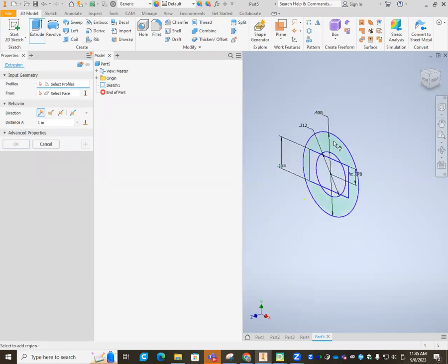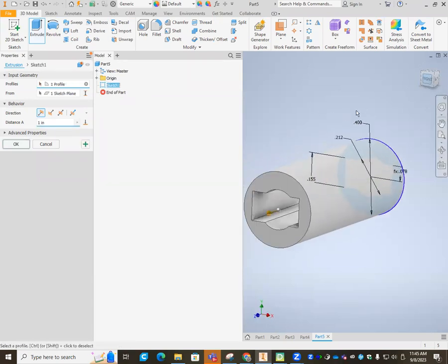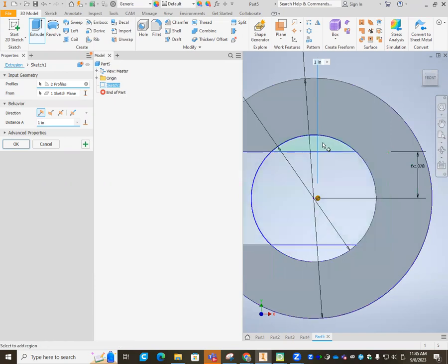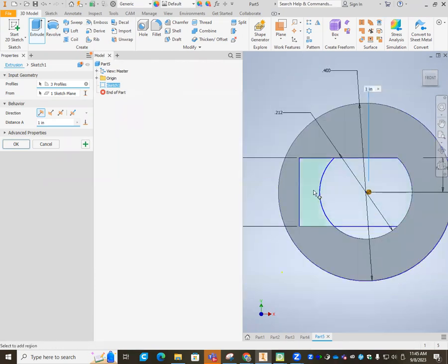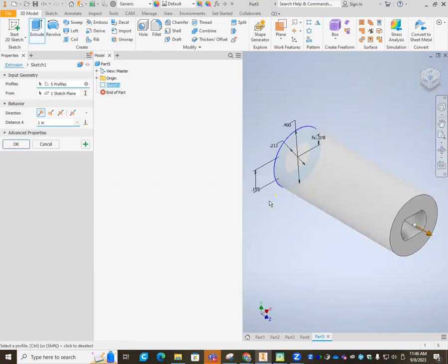For my pros, this is probably where you will be leaving us. You got the critical dimensions, you got the shape down. I'm going to need to come in here and pick out all these so we have this nice circular shape with 2 flat spots on it ready to go. That is what's going to press on to the motor shaft. Press on to the motor nicely. And it's a nice snug fit too. It's not going to fall off, which will be nice. Might need a little bit of fiddling with like a utility knife or something sharp to take some burrs off from the 3D printing process, but that should be fine.